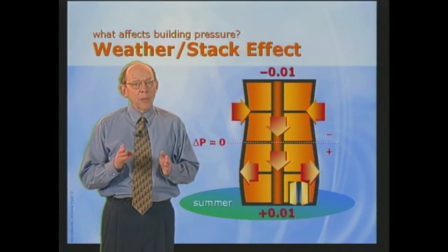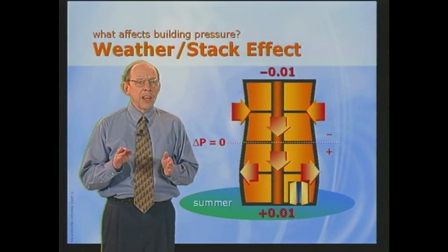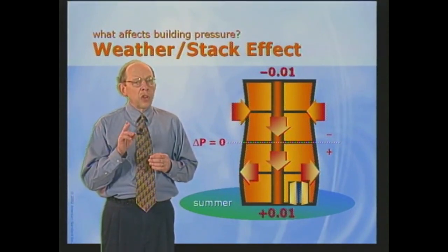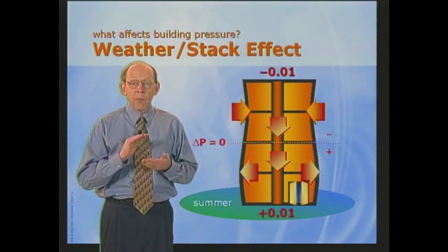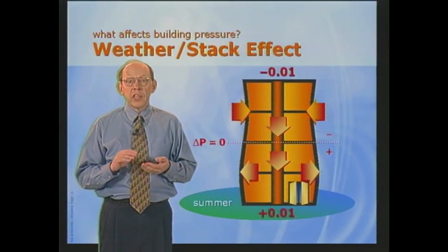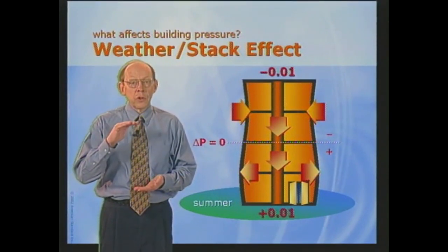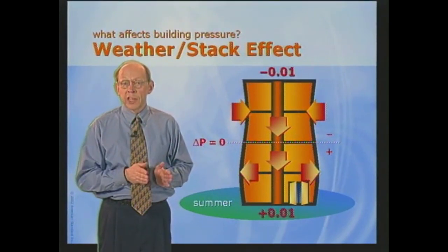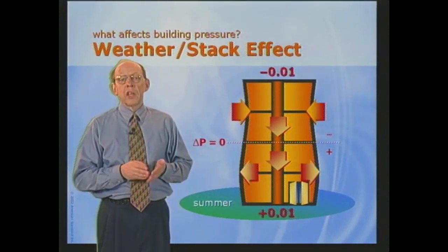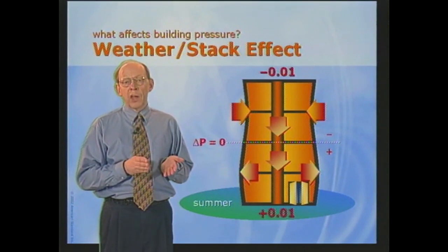Everybody talks about it, but nobody does anything about it, right? Well, you can't change the weather, but if you're the architect, you can minimize its effect by compartmentalizing the building. Good floor-to-floor seals reduce the indoor air column height, which reduces stack effect pressure across the building envelope. The engineer's newsletter that accompanies this broadcast includes more detail on compartmentalizing.